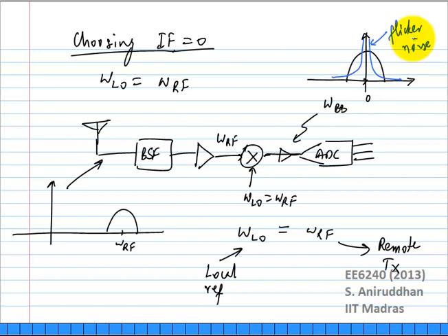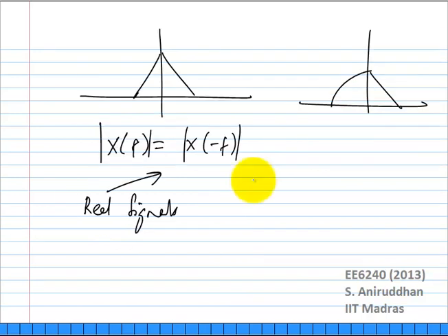How do you modulate flicker noise at higher frequencies? What does the chopper do? Take me through this. I have an amplifier, and I have an input signal here. I want to get A times Vi. This is an amplifier of gain A. How do you chop this to move flicker noise to higher frequencies?